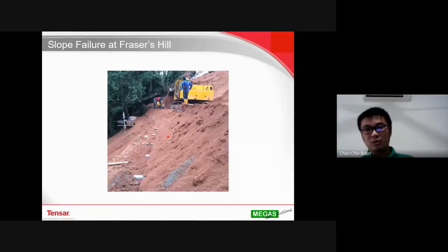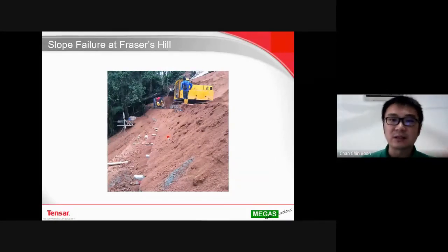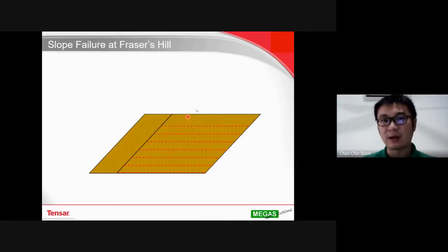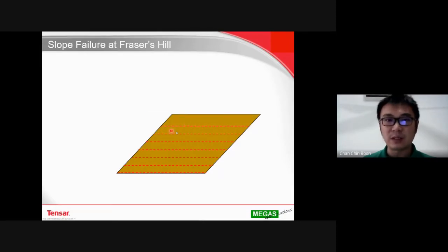So in slope construction, there's always a concern about the stability of the surface. We want the slope surface to be compacted as much as possible. During this construction, you can see that after we compact everything, the surface seems loose. But the right method is to carry out the slope construction by overfilling a little bit in front of the slope profile that we want to form. Then compact it up to a certain level, and we trim it.